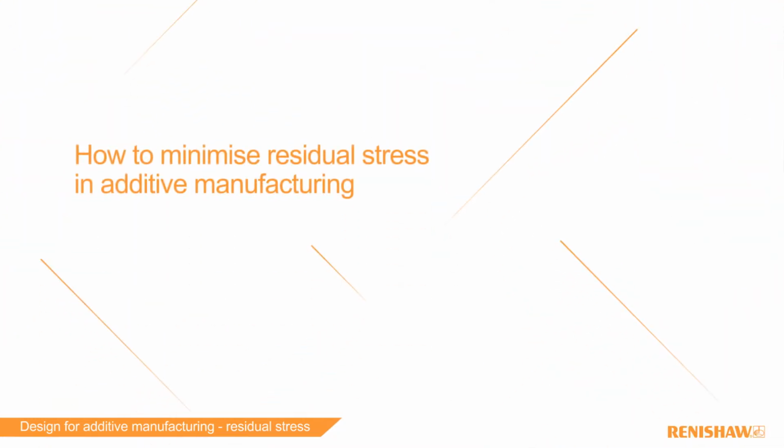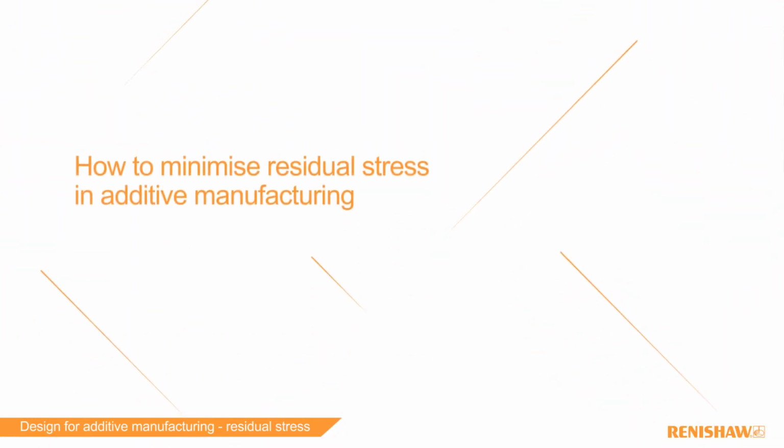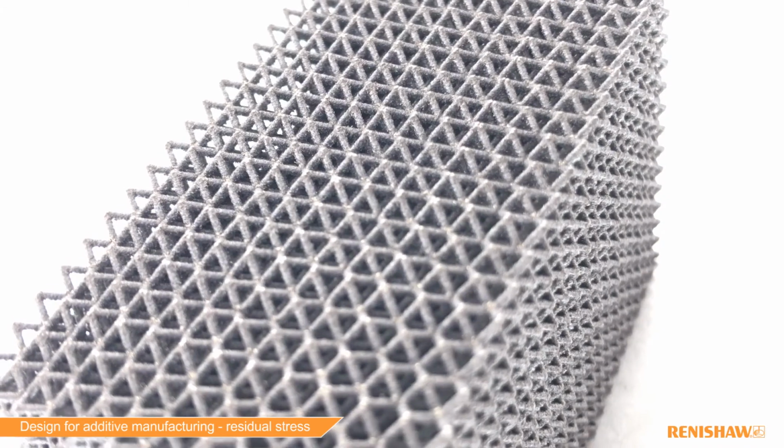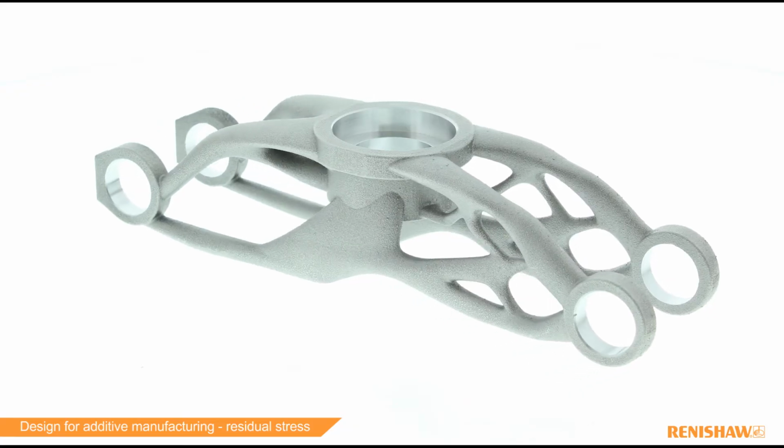So how do we minimize residual stresses in additive manufacturing? One way to tackle this is by varying our scanning strategy, choosing a method that is best suited to the part geometry. When we are filling in the center of our part, an activity known as hatching, we typically move the laser back and forth. The pattern that we choose affects the length of the scan vectors, and hence the level of residual stress that we are likely to build up in our component. Strategies with shorter scan vectors will generate less residual stress.